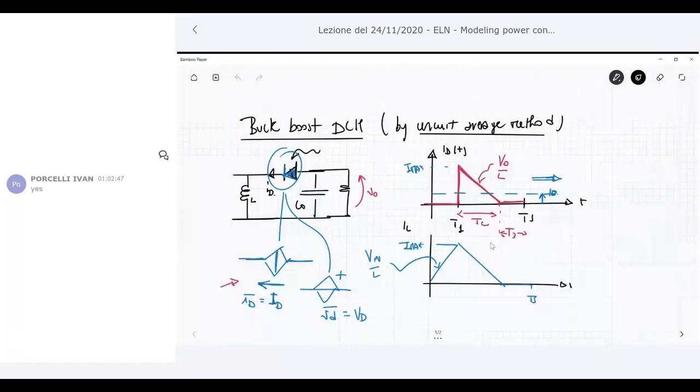The main idea is that look at your circuits, look at the components that are responsible for, say, the variable structure, so the time variant behavior of the system, so the switches, diode and MOSFET transistors, and try to replace them by a dependent current source or dependent voltage source that take into account only the average behavior over a switching period. Okay, which circuit I have to say replace?